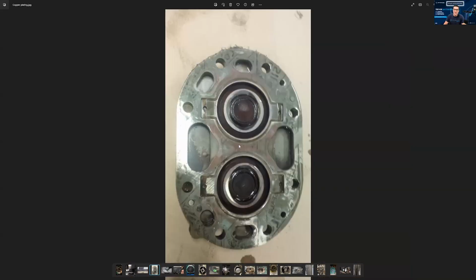But for this here, if you see this stuff, you need to understand what caused that, because you could have an electrical failure, and if you didn't open up that compressor and you didn't see this, well, what's the issue? One of the things we always had to distinguish was the difference between overheat and contamination. If you can wipe it clean with your finger or a rag easily, it's probably not overheat. That's one thing to think about too. If it comes off easily, it's the oil being contaminated and it's causing some problems.